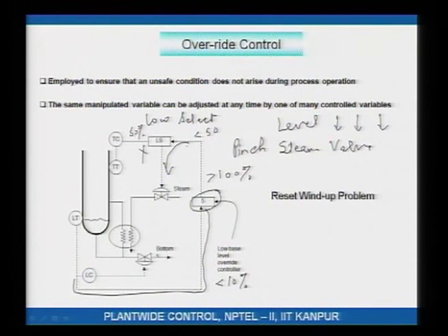ordinarily this would be going through, the PI controller will keep integrating whatever is coming from here, and that can cause this output to saturate beyond 100%, way beyond 100%, and this is known as the reset wind up problem. Those of you who do not know about it, it is covered in reasonable detail in any basic controls textbook.